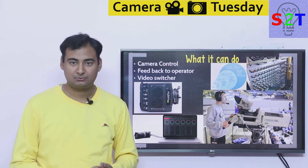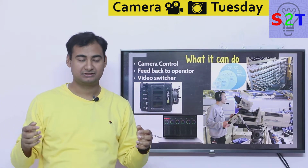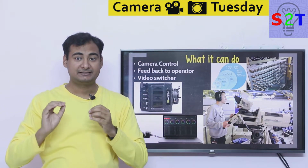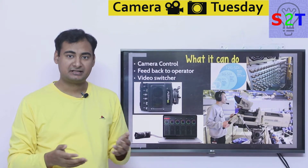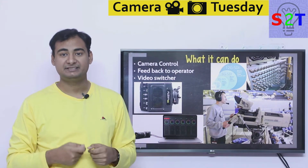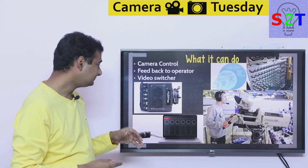Basically, if you are in a production environment like a TV studio or Big Boss or things of that nature, even in Big Boss or Big Brother in your country, they have cameras that can pan, tilt, zoom and all that. That is only happening because of SDI. You might think it can be done over Ethernet, and Ethernet has the benefit of what we call power over Ethernet, so you have only one cable. The problem is Ethernet does not have enough bandwidth. SDI has enough bandwidth to do that. So this is why we use it.